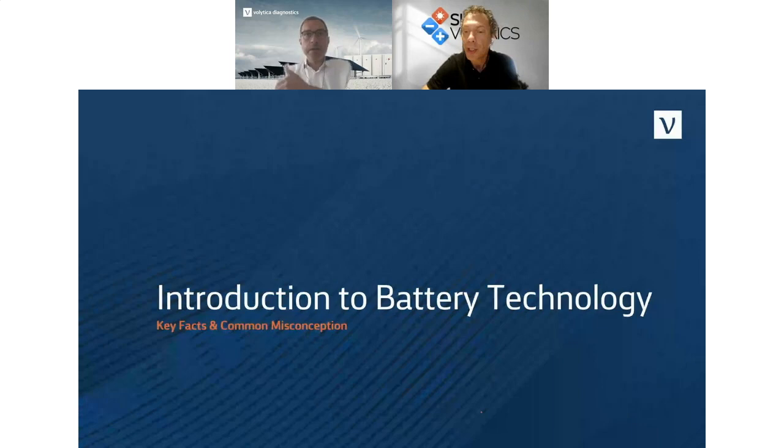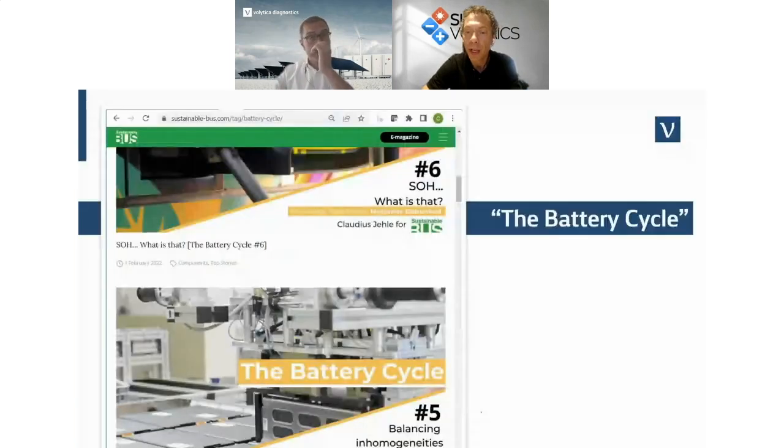Just a quick question from Giovanni. He's asking, what's the time resolution of the battery data that you use? The very short answer is 1 reading per second of voltage and current is ideal. We can deal with a little bit lower resolution, but typically 1 second for BESS is available due to the warranty contracts anyway. 1 second. Okay, thanks.